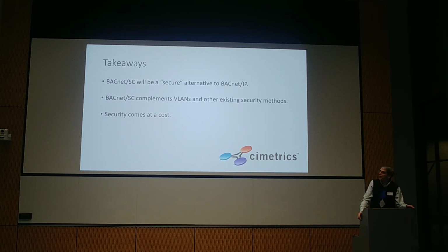BACnet SC will be at least a more secure alternative to BACnet. It's intended to complement other security methods that IT departments or facilities departments might implement to increase the levels of security. But of course, security comes at a cost, and not everyone's going to want to use it because you have to maintain infrastructure in order to manage certificates, among other things. If anyone's interested, we can talk about some of the details of that offline.